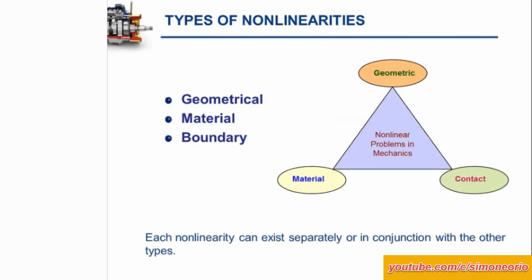Well, in a finite element model, we can have three types of nonlinearity. One would be geometric. The shape of the part is changing as the load is applied. So when we have those types of conditions, what happens is that we apply a small percentage of the load in the analysis. We look at the stiffness and the shape of the model, and then we apply more load to flex the model, and we do it in steps.